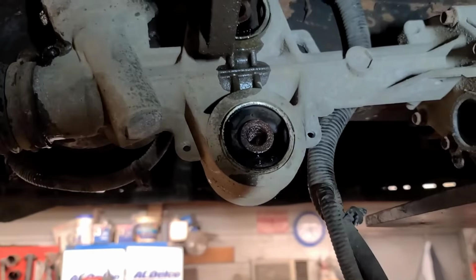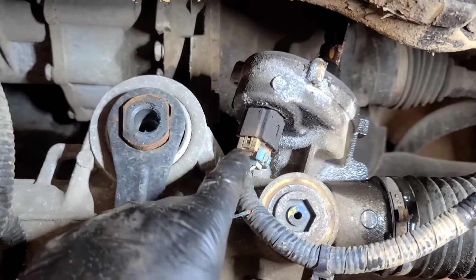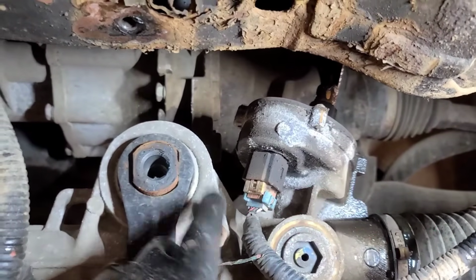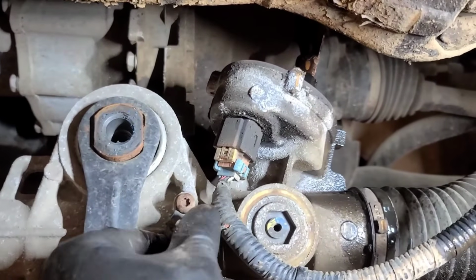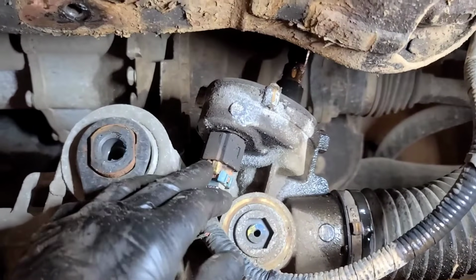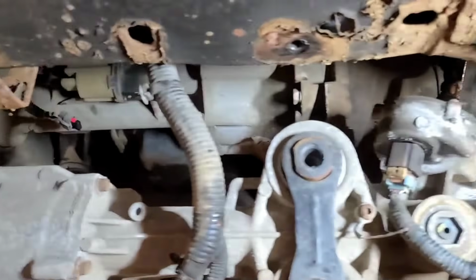Make sure the harness is all disconnected. There's a bunch of clips on the harness as well. Okay, I missed this connection on this side here at this torque angle sensor. I would imagine that's a torque sensor and position sensor. And then there's another ground wire. These must be shield grounds. I don't know why they have to use a T25 on it, but they did. So this connector has to come off as well. It'll rest on the tie rod ends while you're working on it at this height.